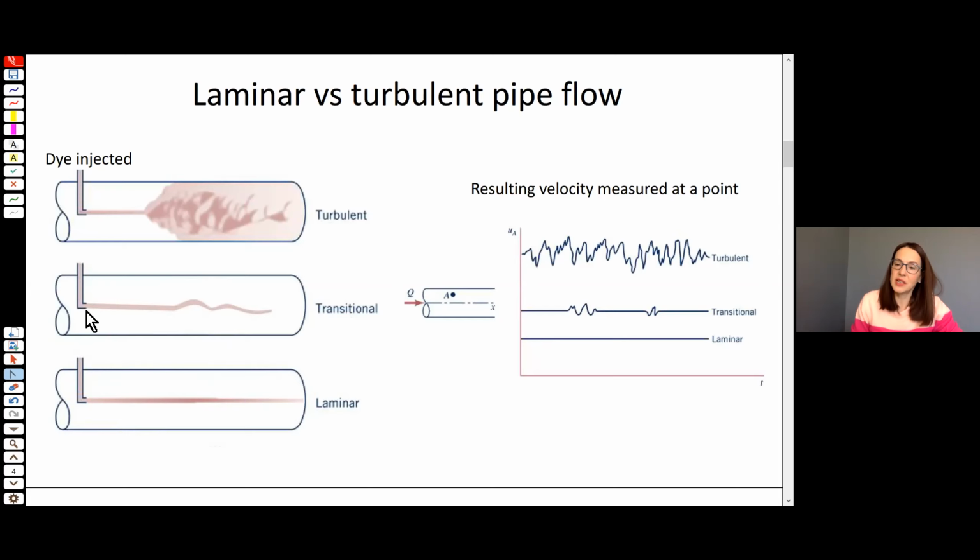If you raise the velocity in the pipe a little bit, you'll have that nice, straight, smooth line, but then every once in a while, you'll have a little hiccup, little sort of random behavior. If you raise the velocity even more, then you're in the turbulent flow regime. You inject dye, and you can see the streamlines, the streak lines of the dye are just chaotic, and they trace out three-dimensional paths, right? And that's really what characterizes turbulence, that chaotic, random, small-scale motion.